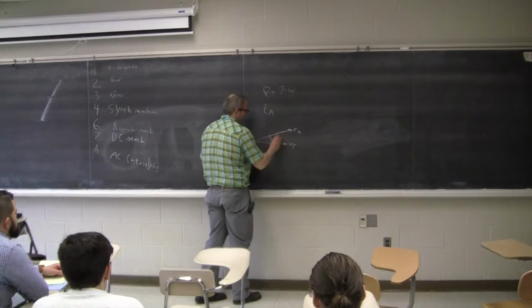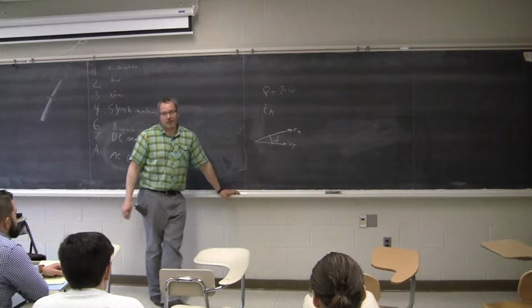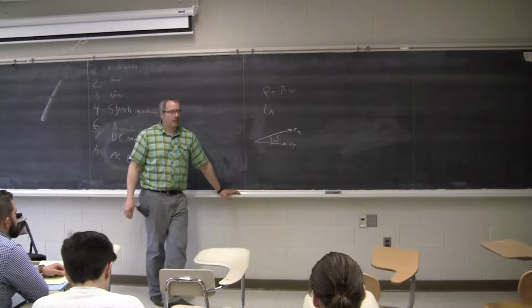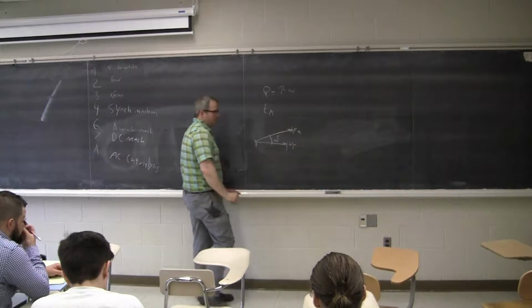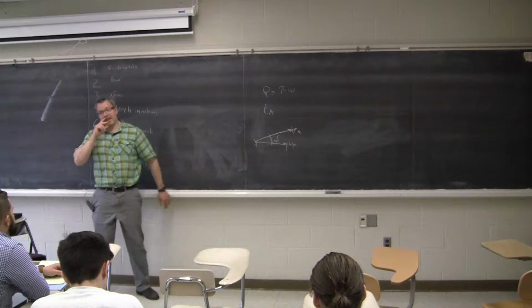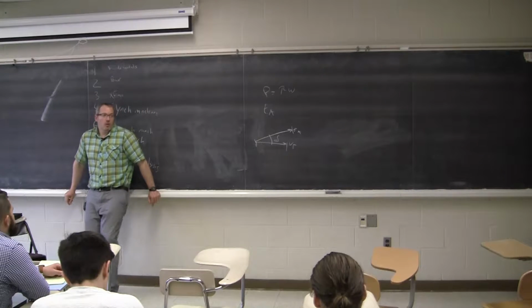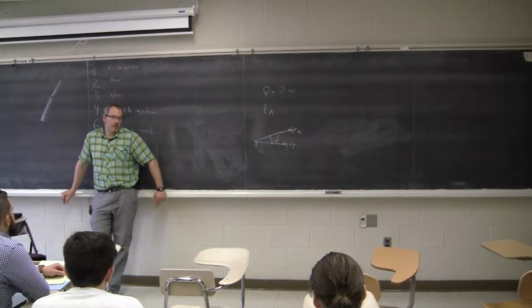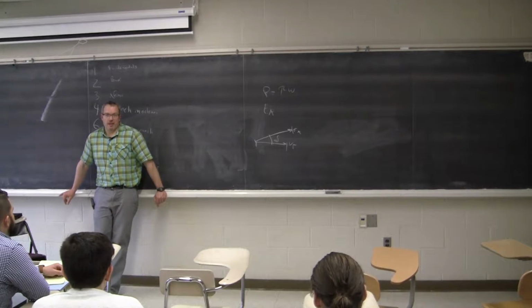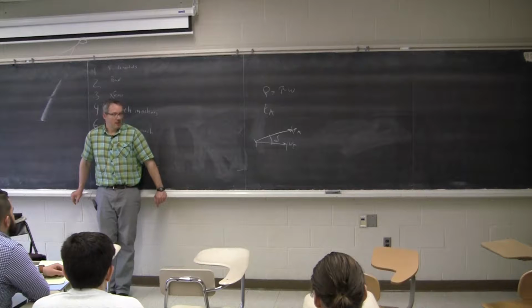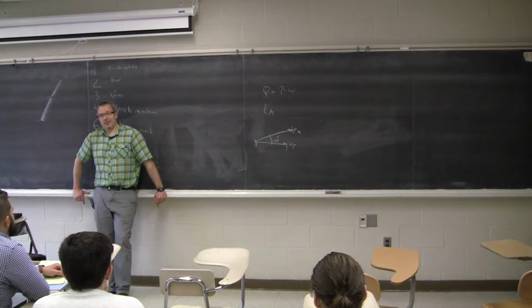This angle tells me if it's a motor or a generator. The magnitude of this as compared to VT tells me if it's a reactive power load or reactive power source, just by looking at the phasor diagrams. So you're trying to get some really quick understanding of things. Drawing phasor diagrams makes things really useful.